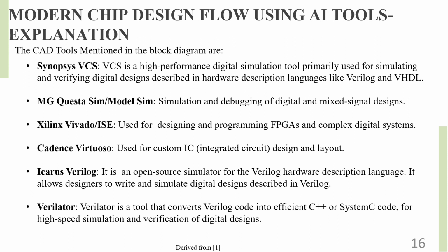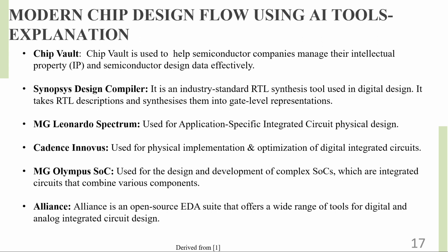Verilator. It is a tool that converts Verilog code into efficient C++ or SystemC code for high-speed simulation and verification of digital designs. ChipVault. It is used to help semiconductor companies manage their intellectual property and semiconductor design data effectively. Synopsys Design Compiler. It is an industry standard RTL synthesis tool used in digital design. It takes RTL descriptions and synthesizes them into a gate level representation.